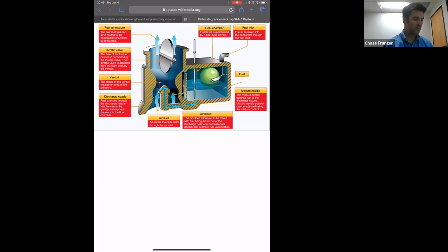Why do I need to know this? Well, because when you run out of gas, it's a really bad day. There are several reasons. As we pre-flight the airplane, it's important to note that we have a proper amount of fuel, and the right type of fuel. Jet fuel, for example, is straw in color. Our airfield, Montgomery, has jet fuel. If they fill up our aircraft with jet fuel, it'll start, it'll run up, it'll apply full power just fine. The engine will die shortly after rotate. Probably the most inopportune time for the engine to die.